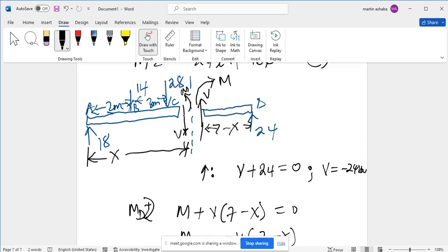I'm saying if I consider the bending moment moving the other way around and the shear force moving downwards, then on the other side, the bending moment will move the opposite way to this, then also the shear force will move upwards. Then if I said that section is at a distance x from A, then the last part reaches up to D, and if I add this part and that part it makes a complete beam from A to D and its length is 7, then if from A to that point is x, it means the remaining portion will be 7 minus x.